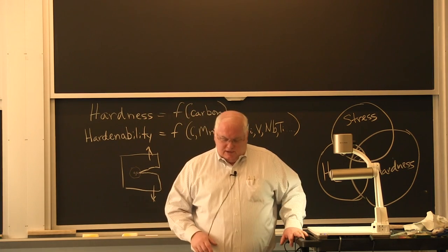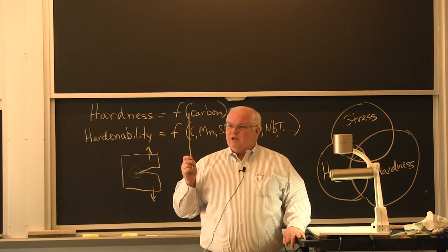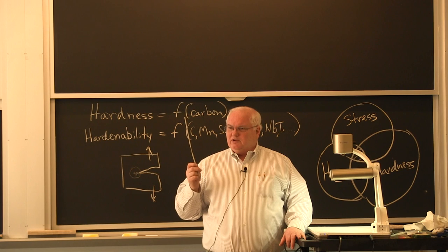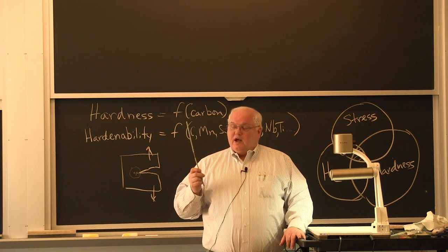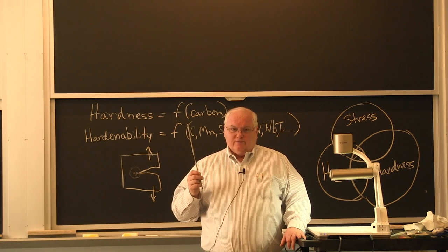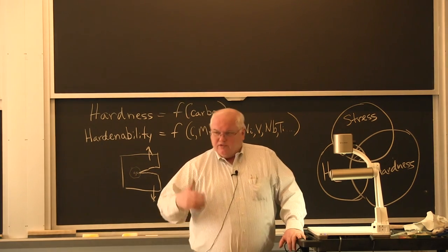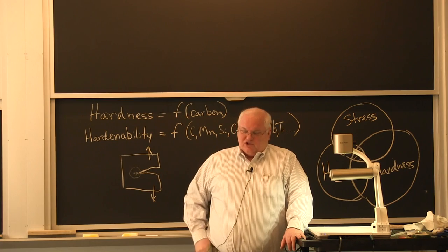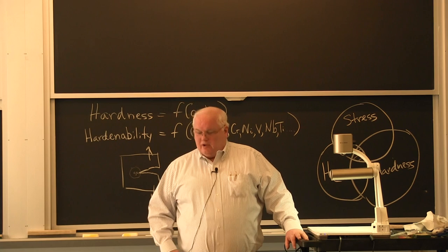And typically, the 7018s have to be kept in a rod oven at about 200 degrees or 250 degrees Fahrenheit, and used, if you're dealing with high strength steel, sometimes used within 1 hour of taking them out of the oven, because they'll start to pick up moisture right away. And it's a question of how much moisture. I'll get into how much moisture, but I think your question is how long can I leave them out? Cellulosic electrodes you can leave out for a year, because we didn't try to drive the hydrogen off.